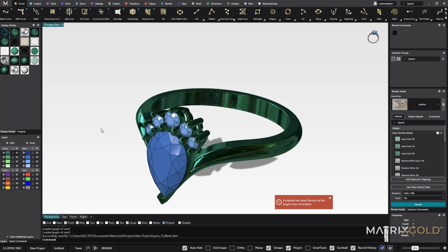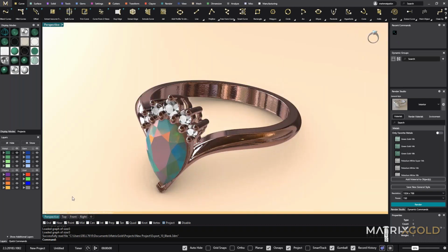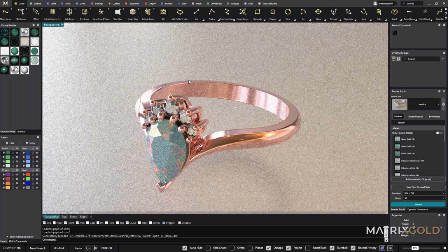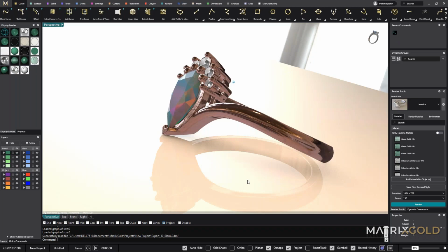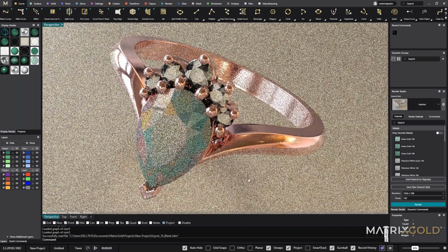Then I'm going to select this rendered active view. When I select the rendered view, it starts rendering. The big window is rendering. I found this option in the Rhino options. It's very good for me. And you can also rotate it. And when you hold off, it will start the rendering.